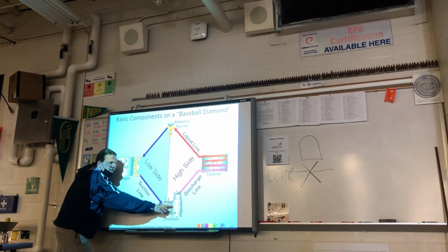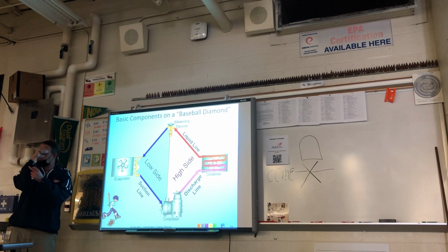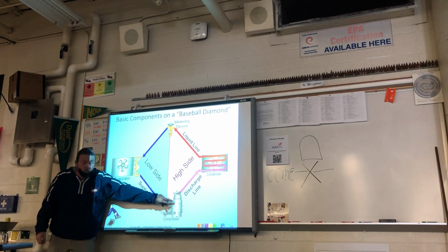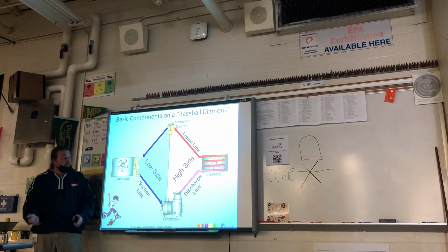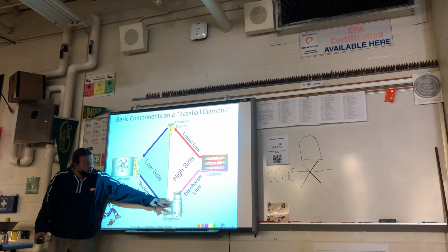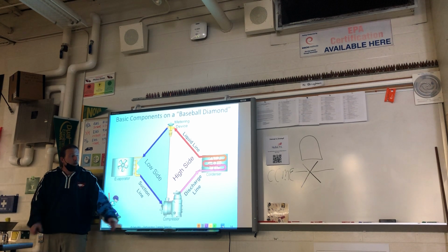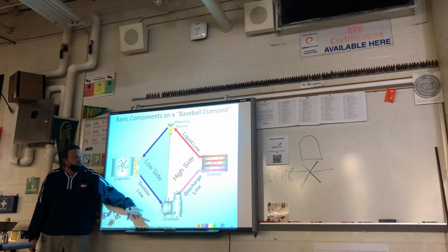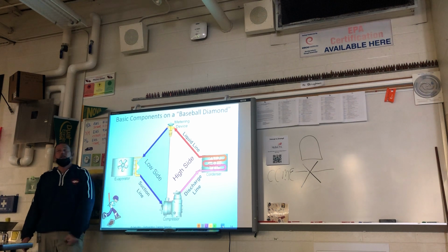Because if we get liquid inside the cylinder, it could damage the piston, the connecting rod could split, the wrist pin could shatter. There's a lot of pieces that can be damaged. The reed valve could snap or be bent, and it's not going to work. Blow a gasket. Something could happen internally to the compressor where it can run, but it isn't going to pump anymore. It's not going to work anymore to where we need the flow of refrigerant happening like it's supposed to happen. So we try and make sure that nothing but vapor goes through all our compressors and nothing but liquid can feed into the metering device.